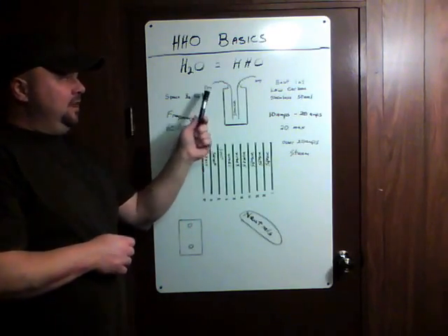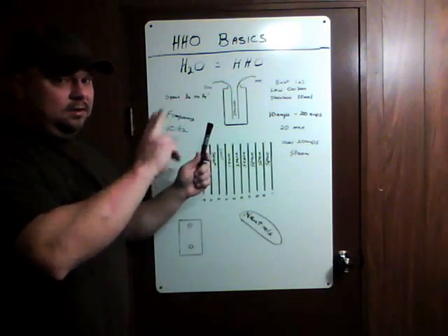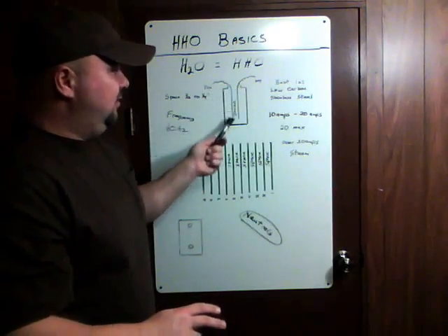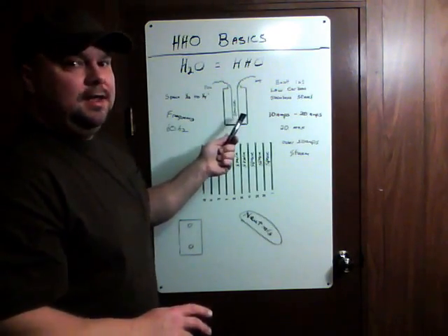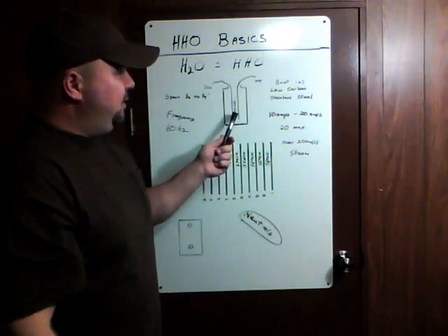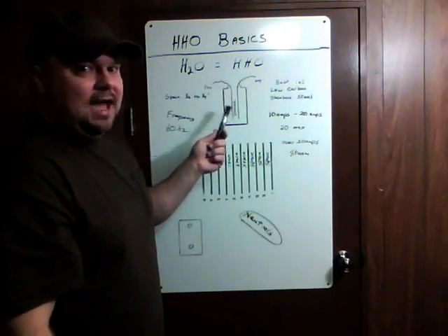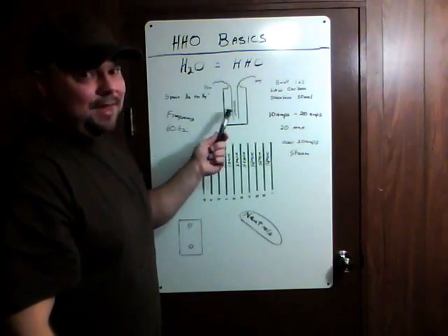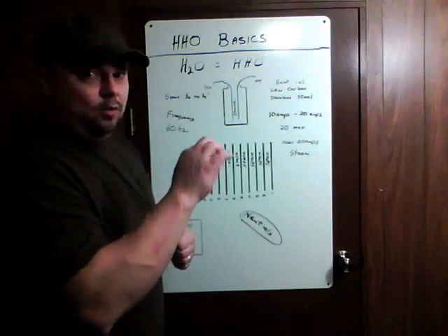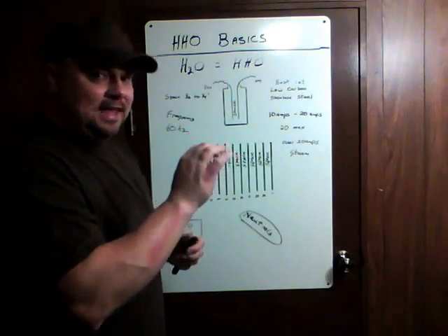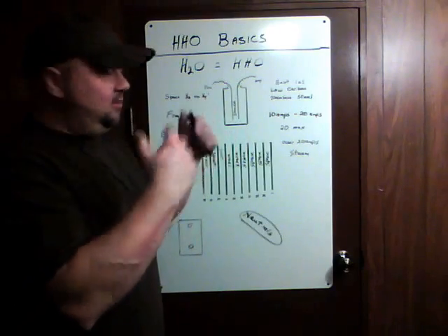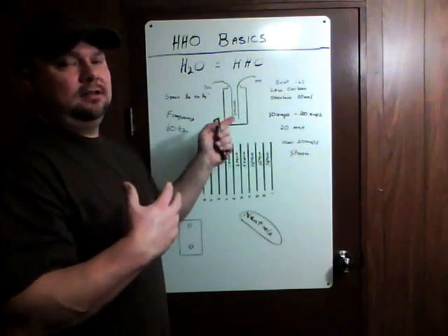In a standard configuration with a one cell unit, no neutral, you've got one plate that's positive. There's a spacer in between. In my video, I use plastic bolts and plastic nuts. The spacer has to be non-conductive. In other words, it can't be metal or anything that will conduct electricity. There are certain rubber gaskets that you'll buy that have lead in them. Those won't work. They'll cause a short. You have to have something that's not going to conduct electricity.